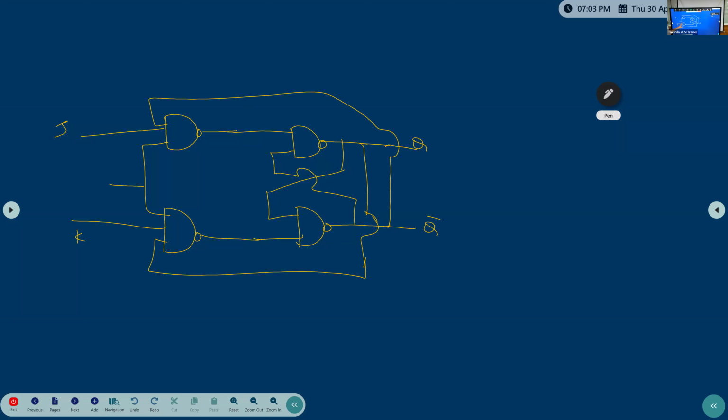Okay, so this is the JK latch. In the JK latch, what is the main problem? Suppose E equal to 1, J also 1, K also 1. Now consider memory is 0. This Q is connecting to the second gate, this one is 0, then output is 1. This Q bar is connecting here. This is 1, this is 1, all are 1, this will be 0. 0 and 1 means it is the set case. Set case, yes or no? For this circuit, it is set case.